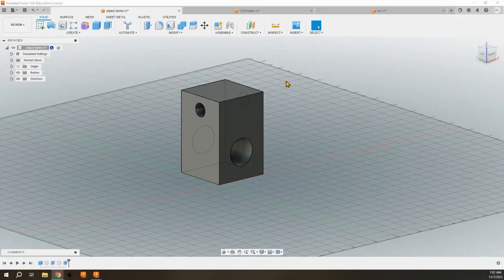All right, we are in Fusion 360 and we're going to learn about how we can take our design here and create a drawing from the design. First thing I want to pay attention to before we even get that far is what is the front side of this? Because the front view, just like when we did this on paper, everything else is based off of that front view. It's central. It's the first view that we're going to place, which you'll see in just a second.